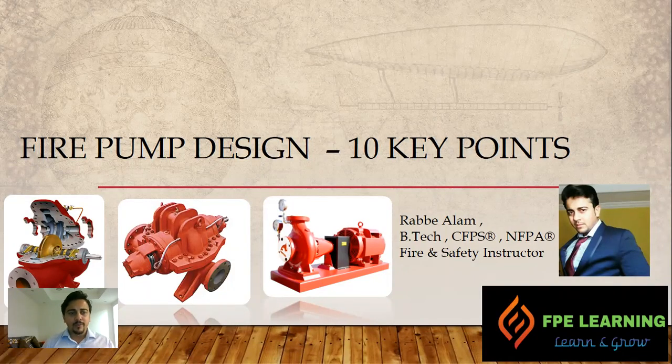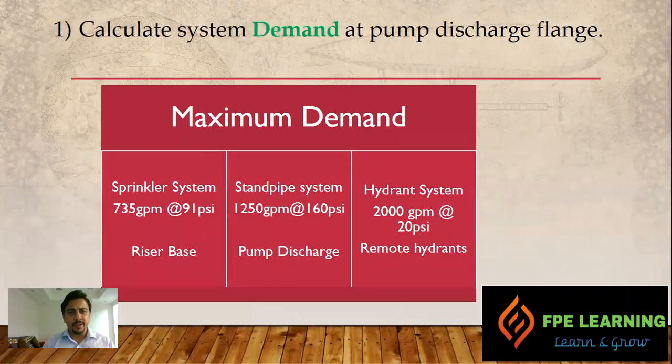My name is Alam and today I am going to discuss the 10 key points to design your fire pump, to select or size your fire pump effectively. So let's start now. The first one, you have to calculate the system demand, right? The very basic, you have to make sure what is the demand needed for your facilities, right?